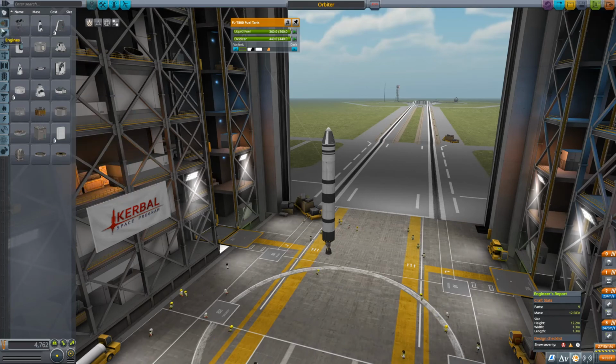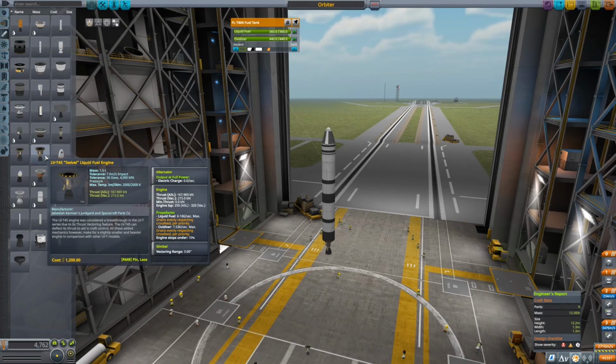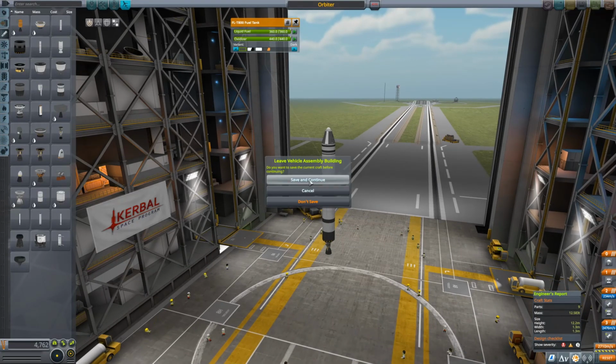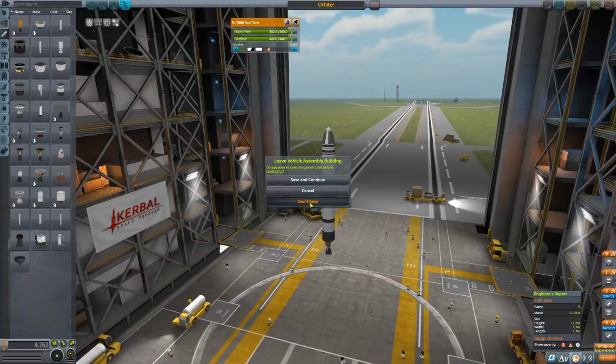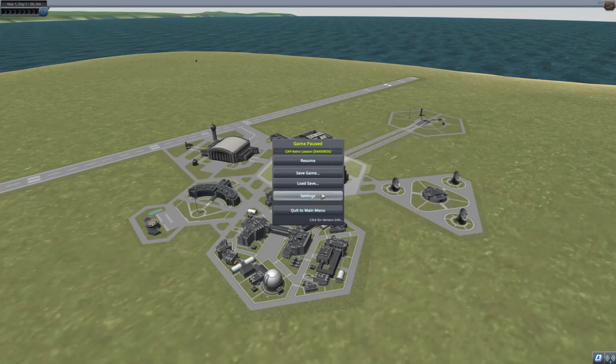And then finally, we can go into the engine that we're using specifically for this and get the engine specific impulse at sea level, and that is 250 seconds. So with that, we have enough information to calculate how much delta V we have here. And notice that it says for this stage, we have 2,476 meters per second. So let's see if we arrive at the same number.